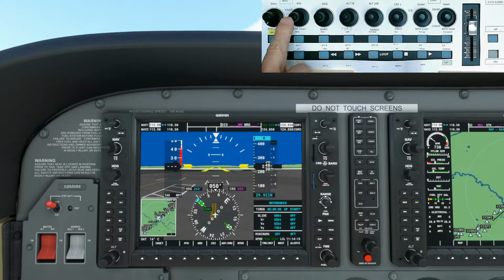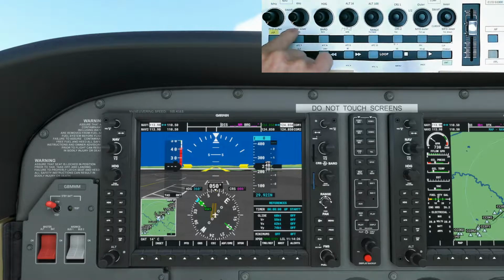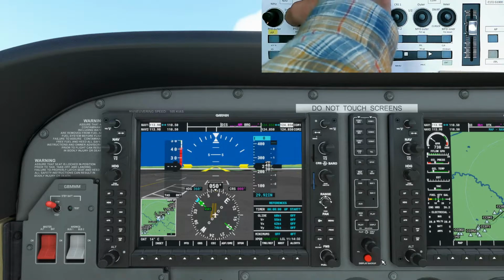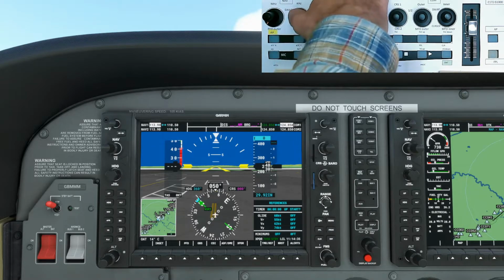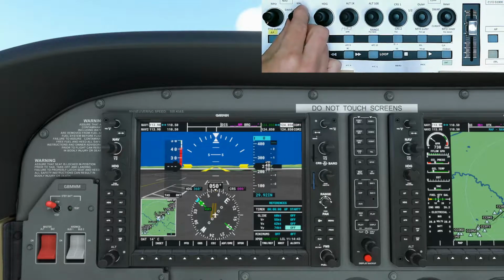So to put that onto here, I brought up the timer and reference here, and I make sure that I am in layer B, because layer B gives us these functions under here, and I'm using this primary flight display outer and inner knob. If I press once on this one here, that gives us the cursor, which we can move using the outer knob down to here, and I want this to be switched on, and I select the on by rotating this.